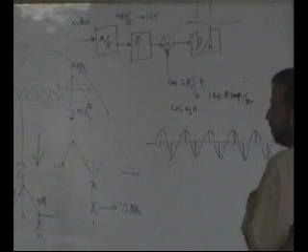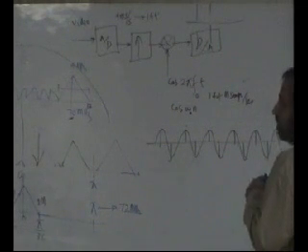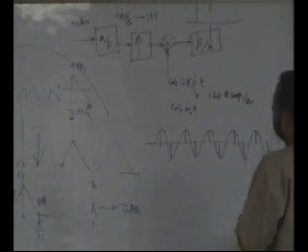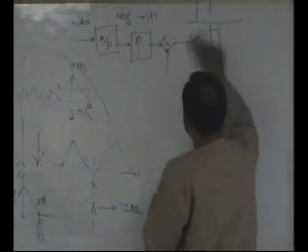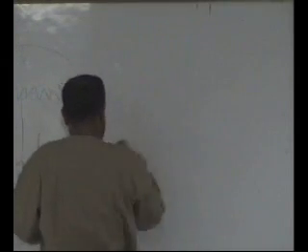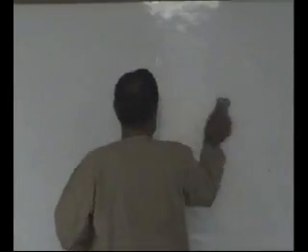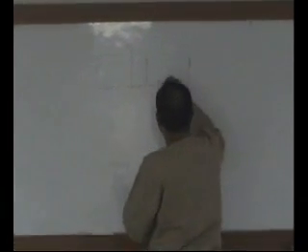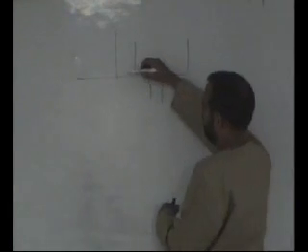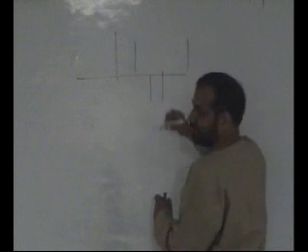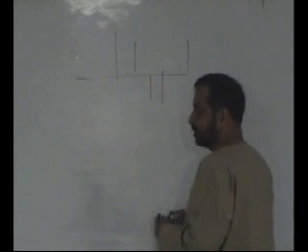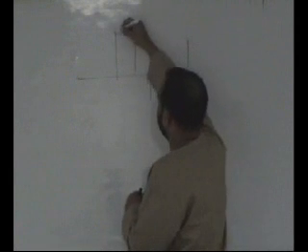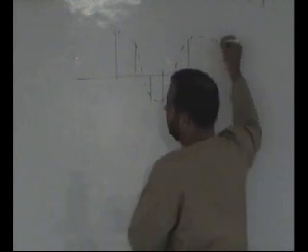When we convert it from 4 megasamples to 144 megasamples, what does that mean? Okay, now this is a good question. It simply means that between two samples, let's say these are your original samples, you have to add 36 more samples between these two samples to bring it up, so that the original shape is kept, though these are redundant samples.